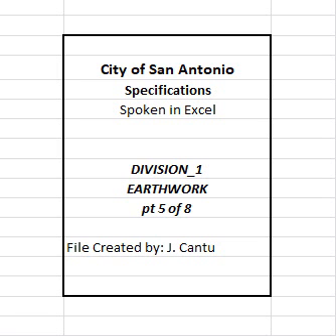C. Embankments adjacent to culverts and bridges. Compact embankments adjacent to culverts and bridges in accordance with Item 106, box culvert excavation and backfilling. D. Compaction methods. Begin rolling longitudinally at the sides and proceed toward the center, overlapping on successive trips by at least 1/2 the width of the roller. On super elevated curves, begin rolling at the lower side and progress toward the high side. Alternate roller trips to attain slightly different lengths.